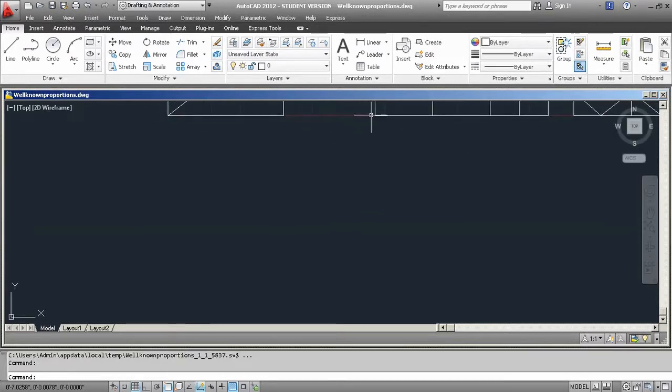Okay, now we're going to make ourselves a room. We're going to start with the line command, and more or less in the middle of the lower left hand corner of the screen, you're going to select a point by clicking with the left mouse button, and then you're going to enter @, which is shift 2. That's going to be a 4-inch horizontal line, so type 4, angle bracket or left chevron mark, and then type 0 because you're going east.